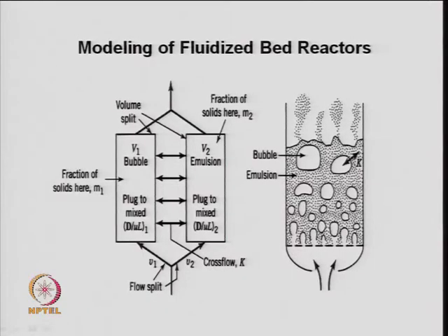The reaction takes place between the bubble phase and the emulsion phase, and there is some kind of transfer of mass from bubble to emulsion. That is the simplest model if you look at the actual hydrodynamics of a fluidized bed reactor. There is another model which is known as the three phase model. In the three phase model, as I was discussing yesterday also, bubbles are covered by solids.